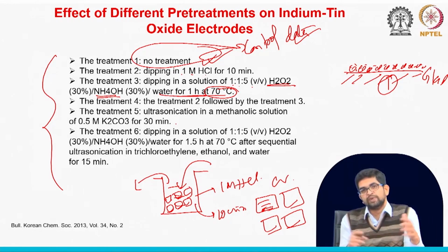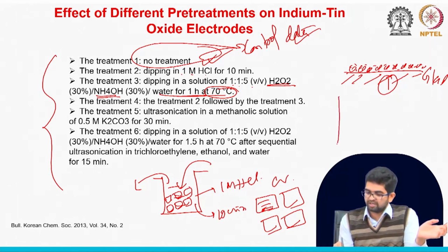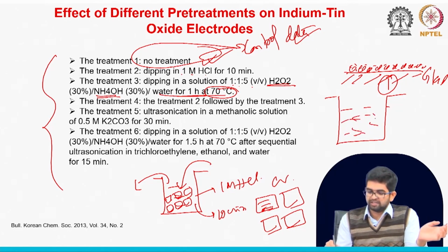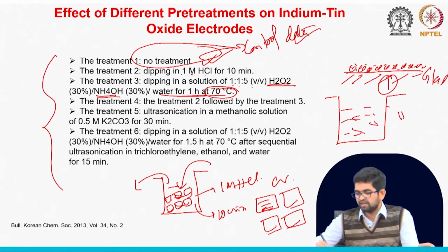They can remove many contaminations like organic contaminations. So like you can take a beaker and you have to take hydrogen peroxide, ammonium hydroxide and water mixture.